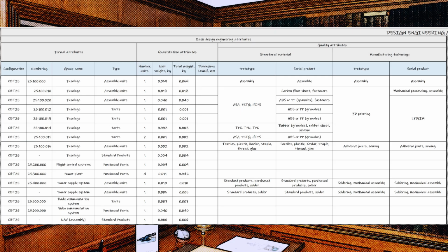For example, for this drone, DIN 912 type screws with an internal hexagon, diameter from 1.5 to 2.5 of various lengths, are mainly used in the fuselage. As a result, all components of the project structure must be decomposed within the framework of the BOM at the stage of serial engineering documentation, except for those indicated in the format attributes block in the type column.